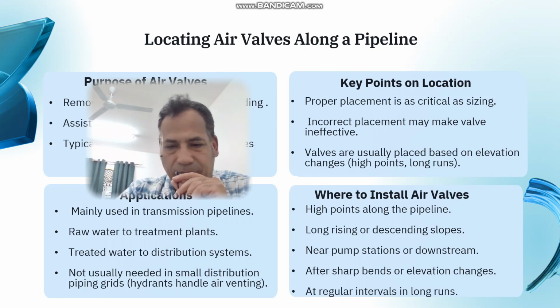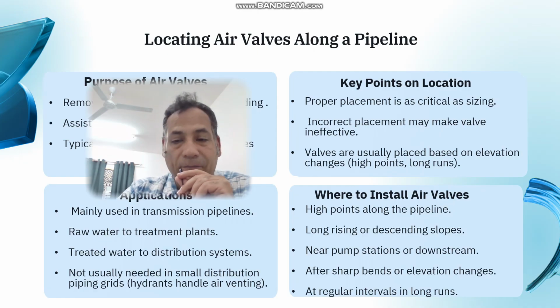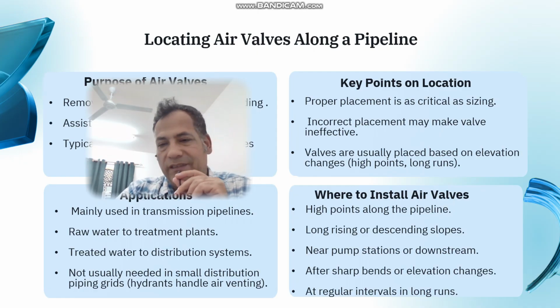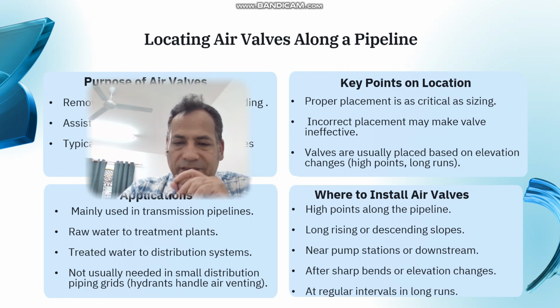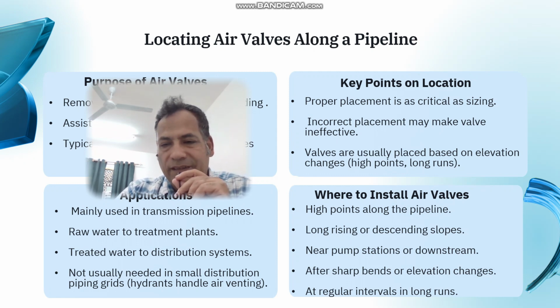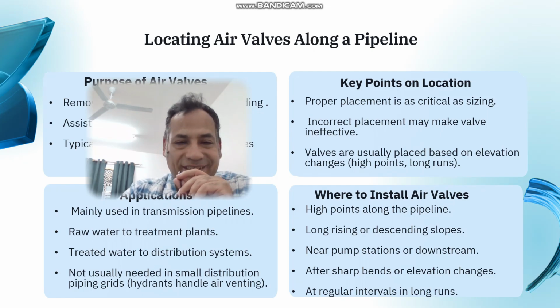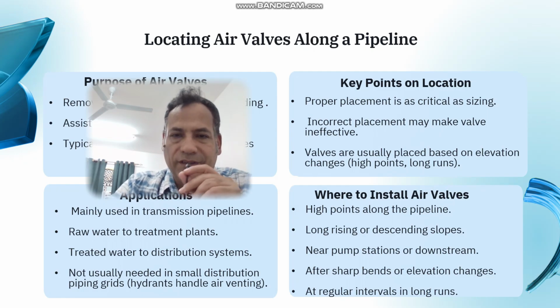High points along the pipeline, I told you, and near the pump station or downstream, and after sharp bends or elevation changes. All these points we need to use an air valve.